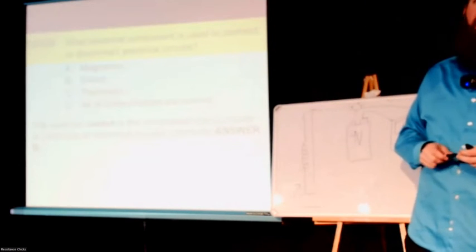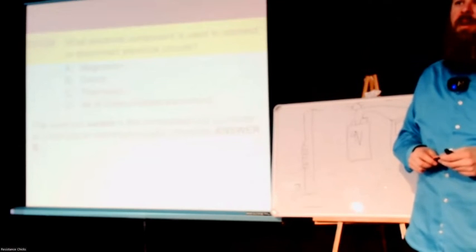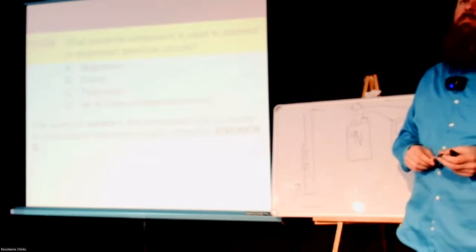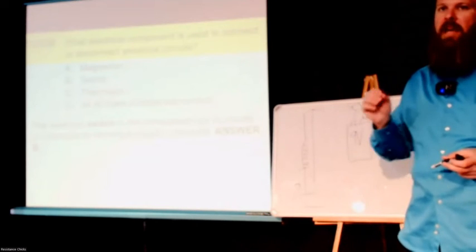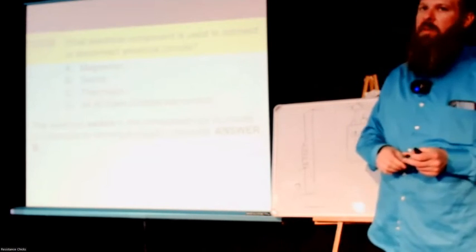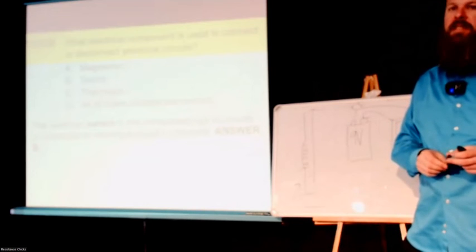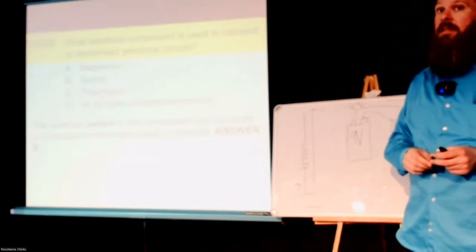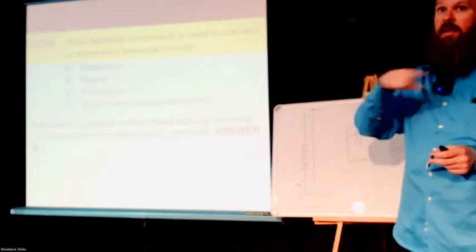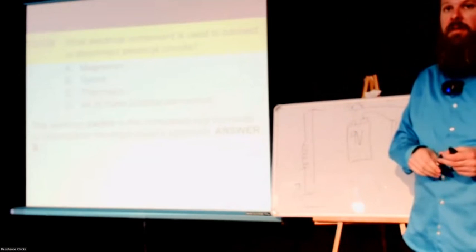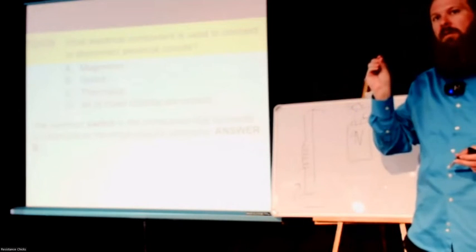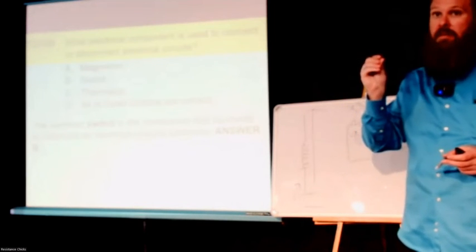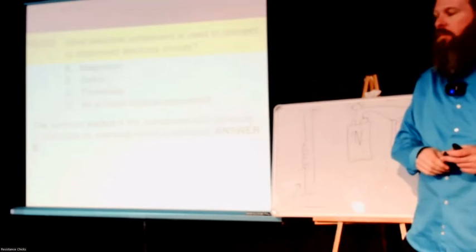So if you're going to build a Faraday cage for your cell phone, which uses sometimes microwave frequencies, you better have a very tight mesh. And in fact, probably the best thing to do would be to build a solid copper box and solder all the edges together, because it's using very small millimeter size wavelengths that can get through small openings.